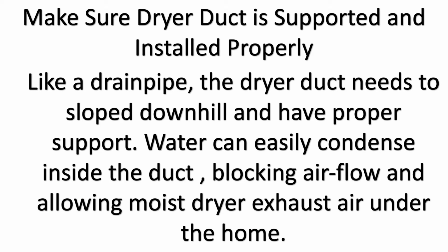Make sure that the dryer duct is supported and installed properly. Like a drain pipe, the dryer duct needs to be sloped downhill and have proper support. Water can easily condense inside the duct, blocking airflow and allowing moist dryer exhaust air under the home.